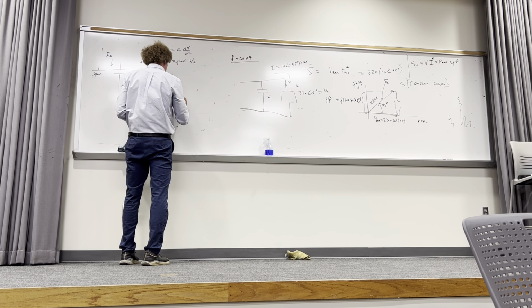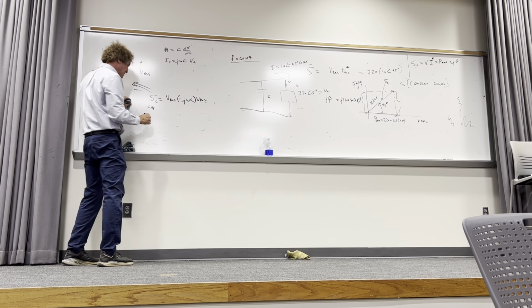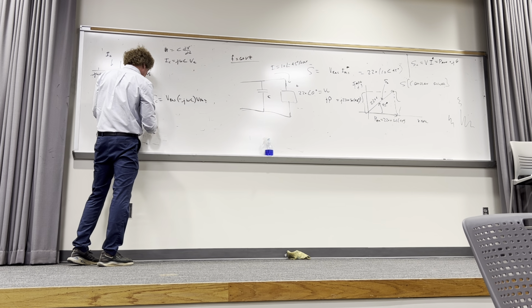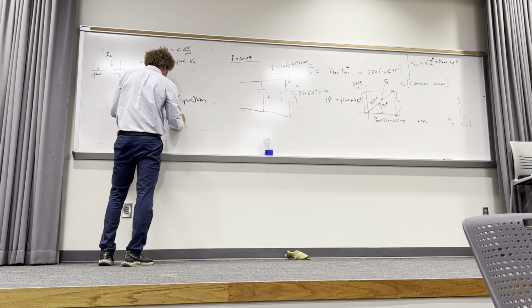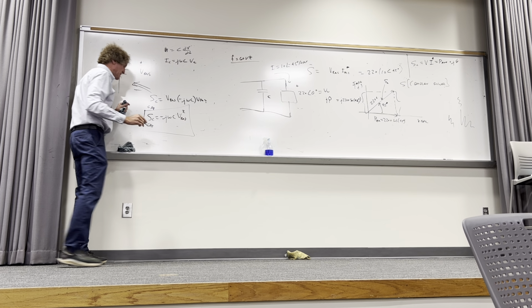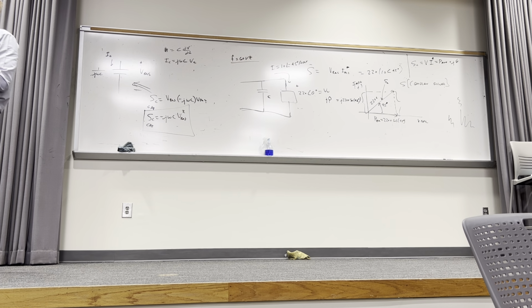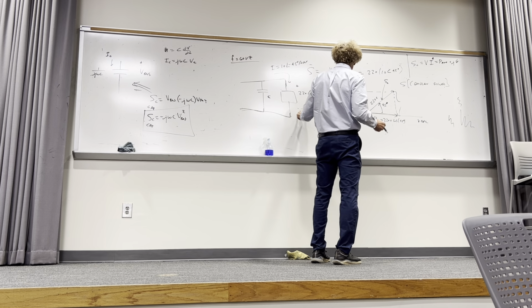So this becomes minus J omega C times VRMS, or simply put, a capacitor has a complex power that is equal to minus J omega C times the voltage across that capacitor squared. And this is the thing you get. Everybody got that? Just write this down. I'm giving you things that you underscore and you have to know. Not may know, not kind of know, you gotta know it. All right. Now, coming back to this problem. The voltage is 220.